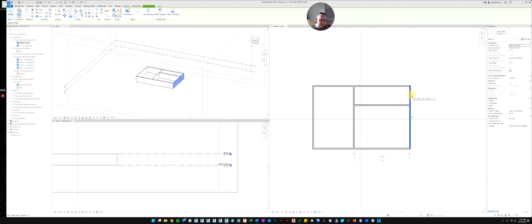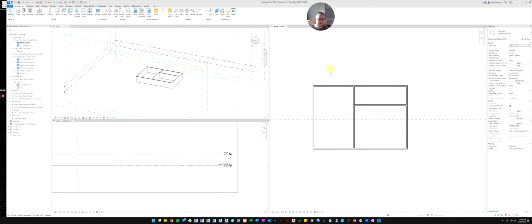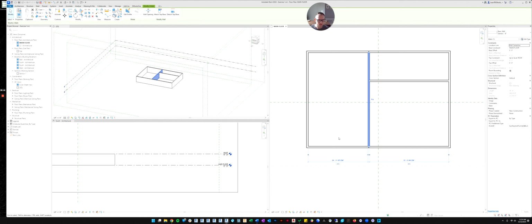So let's do that with the width. Now with the width, we want it to be 60 feet overall, but let's center it on this reference line. So I'm going to move my temporary dimension to the reference line. And then I'm going to move this one to the back side of the wall. And let's do 30 feet because that's half of 60. And then let's do the same thing here. Oops, not 60, 30. So now, if I change the temporary dimension to go from side to side, you can see it's 60.